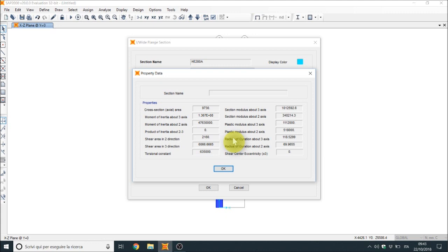This is, of course, the strong axis because we don't have out-of-plane displacement. So if you perform the buckling analysis, your buckling force will be a flexural buckling equal to the ratio between these two values. More or less it will be 12.1. So I expect from the buckling analysis 12.1.